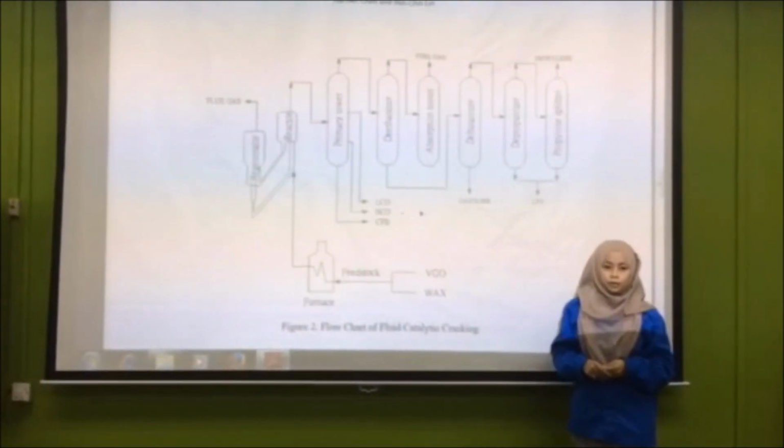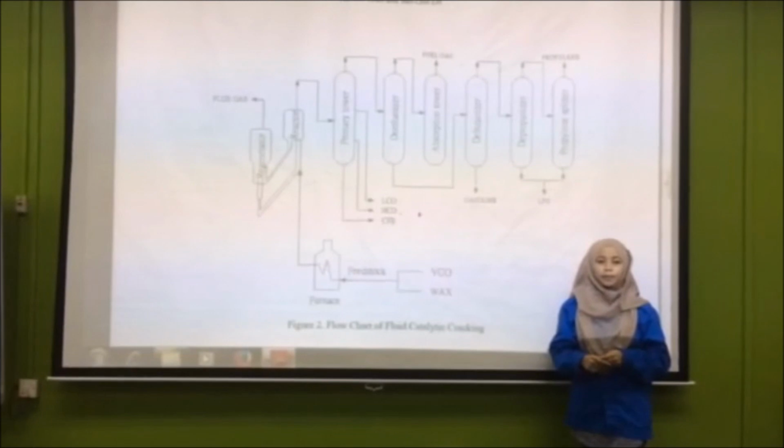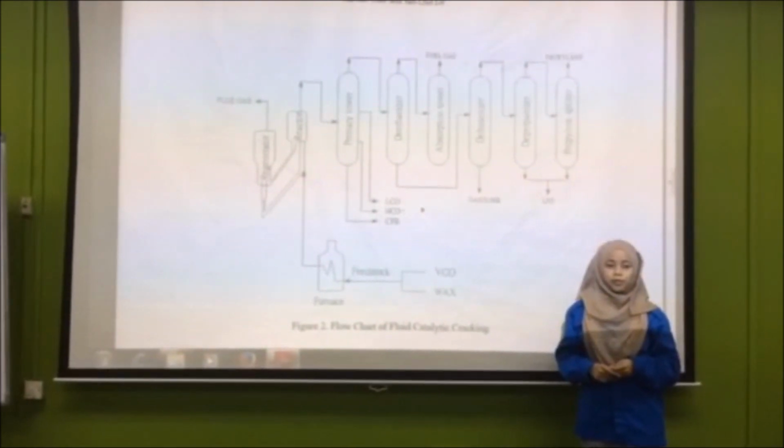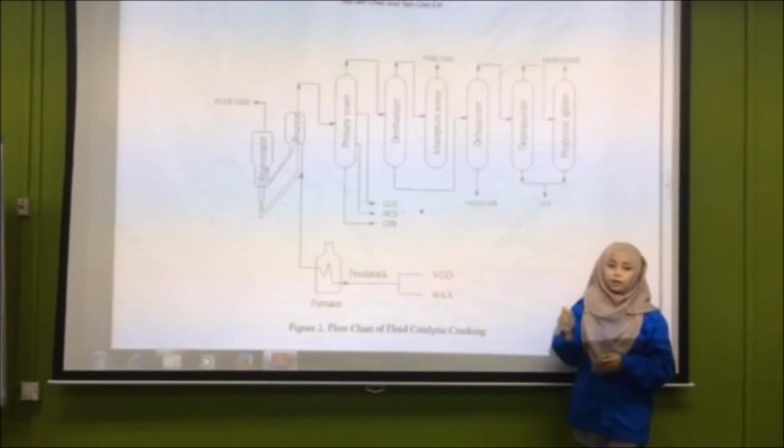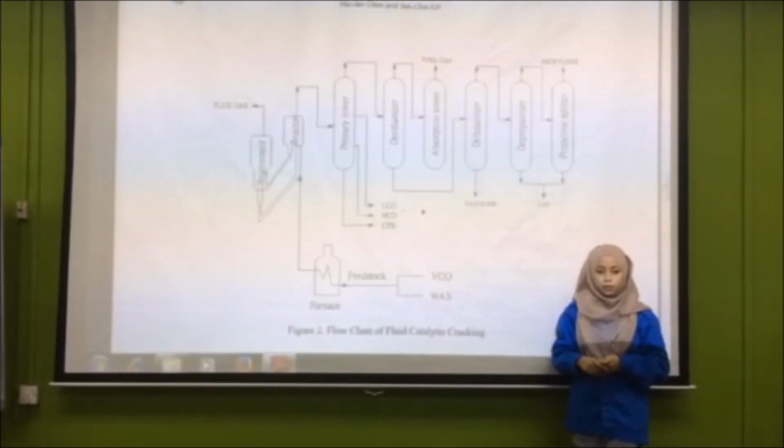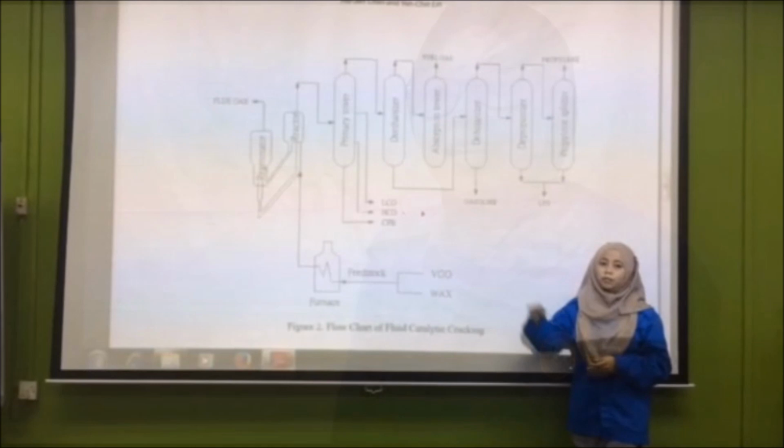A feedstock component list with molar content. This is a multi-component distillation design and is to fractionate between n-butane and i-pentane. We will use design 2 for both shortcut and rigorous design for the debutanizer.